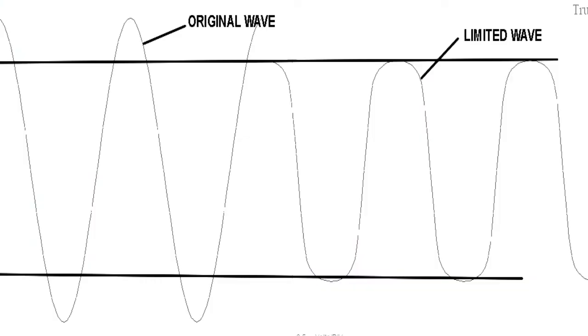The way this soft clipper works is like this. While the overload or spike is present, it's removed by a partial short circuit through a series of diodes. This momentarily distorts the waveform, but it's a very short duration, and the distortion shows as a series of harmonics that appear and disappear too fast to be appreciable. As far as the listener is concerned, as long as the overload was not too extreme, the overload did not exist, and there was no difference to the original signal.